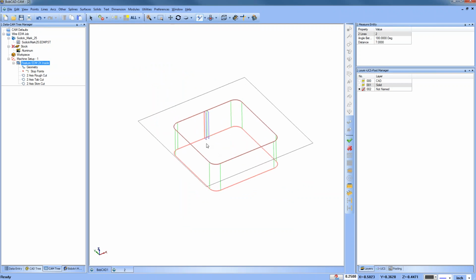All right, let's see. So we have our wire cut path here. We have our start point. We selected our geometry. So we talked about chain selecting. We talked about loop, constant Z. If you want to remove selection, you just go to the geometry, right click and remove. If you want to modify the start point, or right click reselect, I could reselect, right click, modify start point, right click, reverse direction. Is there any questions about geometry selection other than Ronald's? If there is, go ahead and ask it. Otherwise, we're going to move on to the next topic.